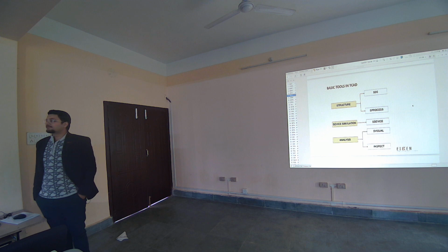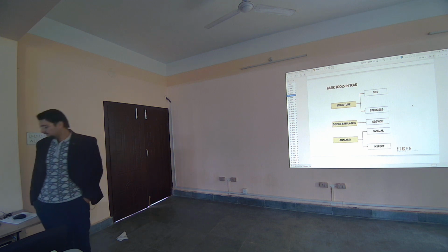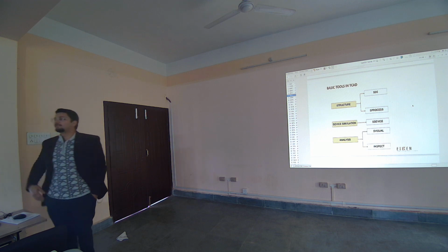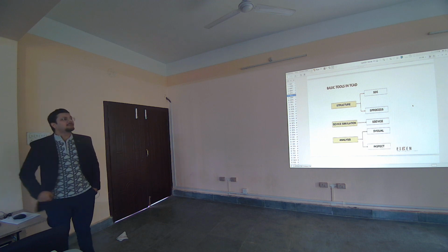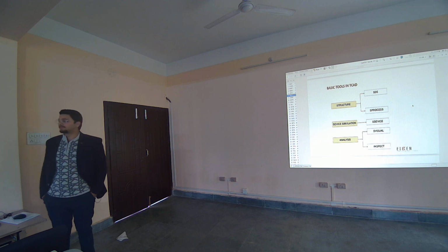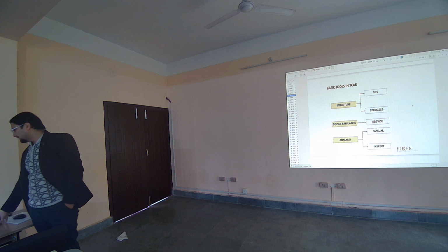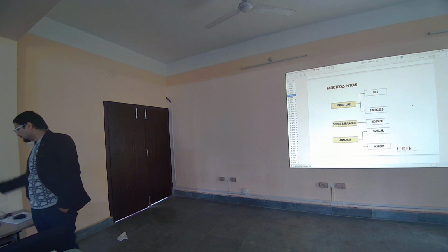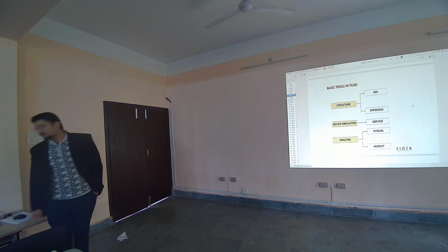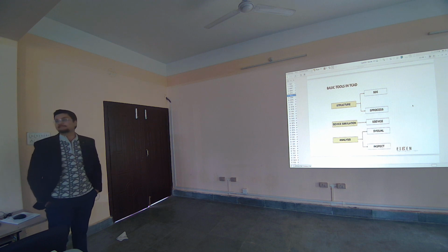SDE and S process both may or may not replace each other in some ways. But in SDE, basically, we are just dealing with the geometry mainly, right? But in the case of S process, we deal with geometry along with the processes itself, right? So you can in some way say that S process is the larger or wider option of SDE. Then we have another tool which is responsible for device simulation. The name of the tool is S device.